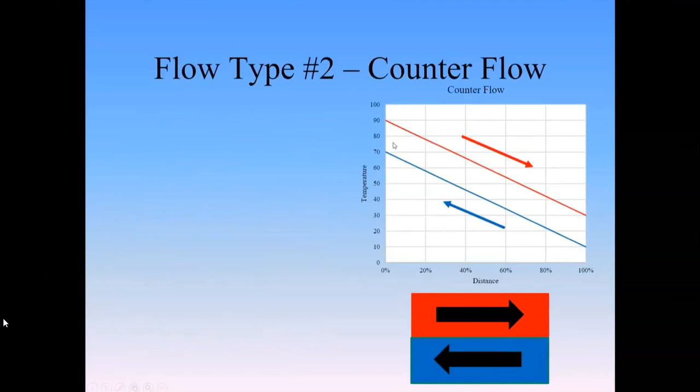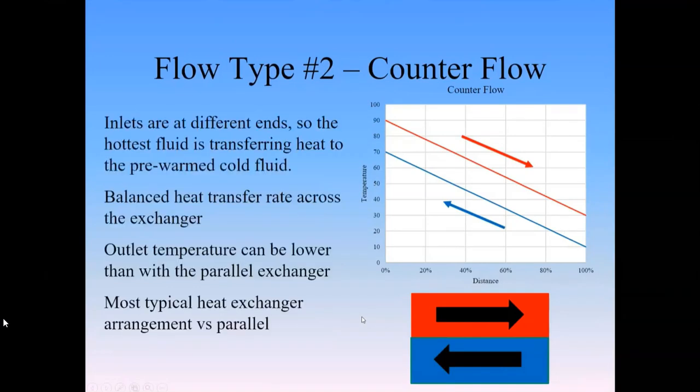This heat exchanger, because it's always a lot more consistent with its temperatures, is set up a lot better in terms of stresses inside that piece of equipment. So we have a couple of benefits to a counterflow. One, we do a better job of heat transfer, so we can exchange more heat, and it's a lot better balanced. For those reasons, you'll tend to find that counterflow heat exchangers are the most common type of heat exchangers that you'll see.